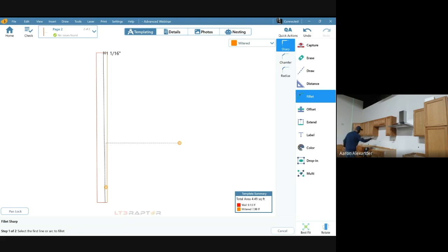So we're going to aim right onto the left side, 2 points to the left side of that cabinet, 2 points to the bottom of that upper, 2 points on the right side of that upper, 2 points on the bottom of this upper, close to the wall. So that's where we set the plane on what we're gluing it to. That's that representation in space. And then we aim onto the objects creating the shape we want to cut the stone out at. That's what we shoot our points on, create these measurements, okay?